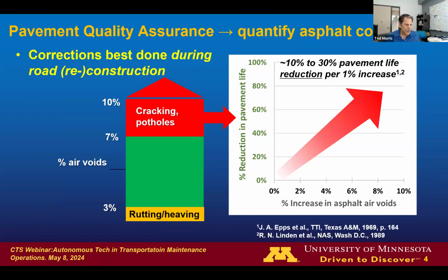But besides that, one overriding factor is that the pavement life itself is very much dependent on how the asphalt, and we're talking about flexible asphalt here today, is actually applied. That is, asphalt that has too many air voids in it really degrades if it goes beyond a certain point, and this is very sensitive to life cycle. A certain point, it really degrades how long a road is going to last.